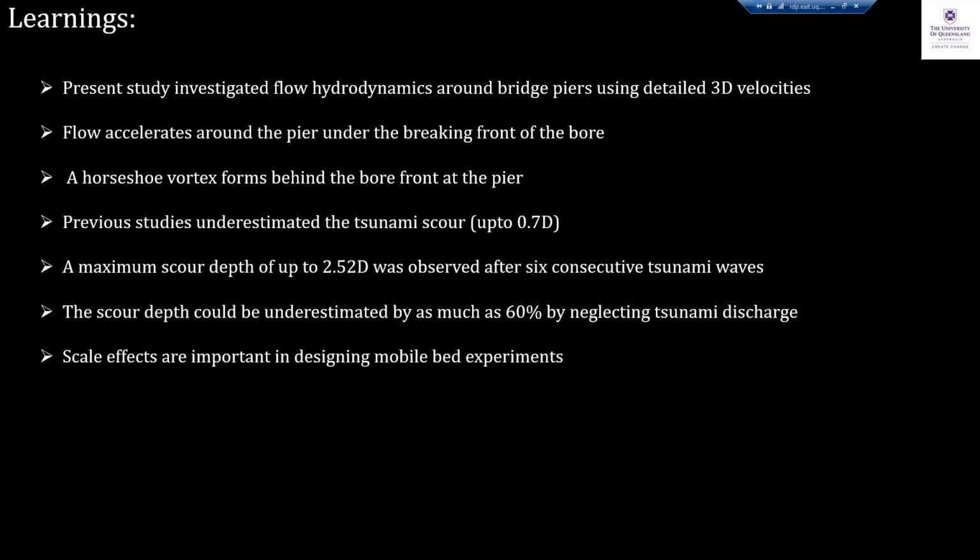And the key learnings from this study were that a horseshoe vortex would form behind the bore front rather than during the total duration of the bore. And this horseshoe vortex is responsible for erosion. And before the horseshoe vortex formation, the flow accelerates around the pier and picks up sediments on the sides. And later on, the horseshoe vortex would pick up sediments from the front of the pier.